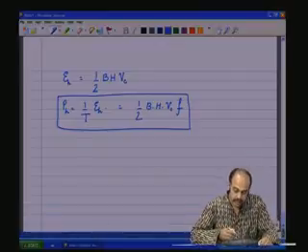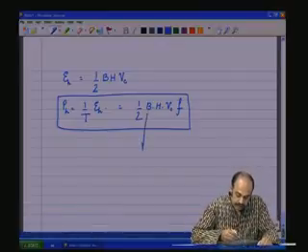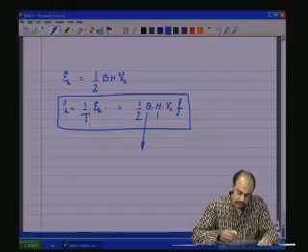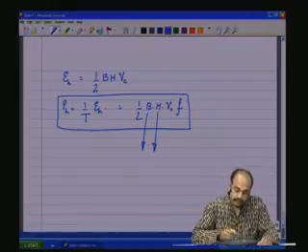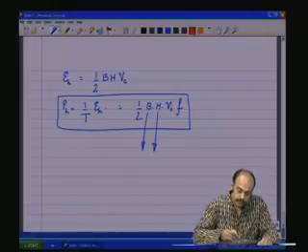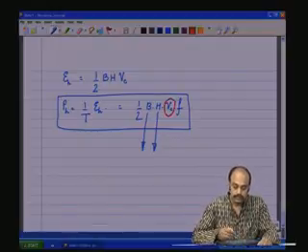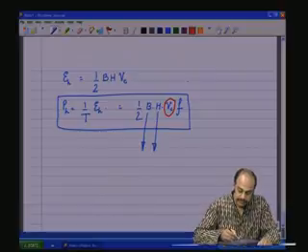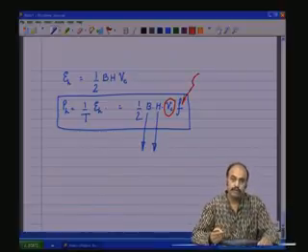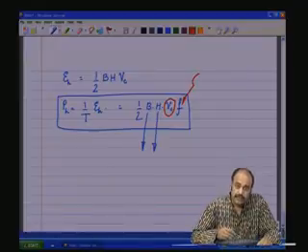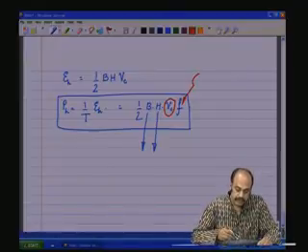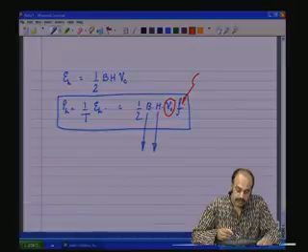See that the hysteresis loss is directly dependent on the flux density, magnetic field intensity, on the core volume. Larger the core, more the hysteresis loss. And another important thing is the frequency of operation. As the frequency of operation increases, the hysteresis loss is going to increase.